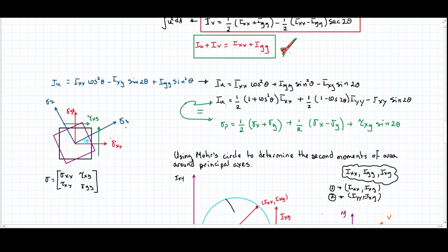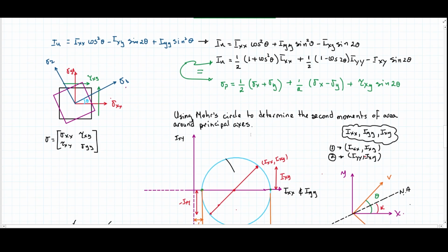Now we said that these equations we found are pretty similar to the ones found in the state of stress concept, where we have a loading case that causes certain stresses, but those stresses might not be the maximum, because maximum stresses are oriented differently, where the shear stresses are 0.